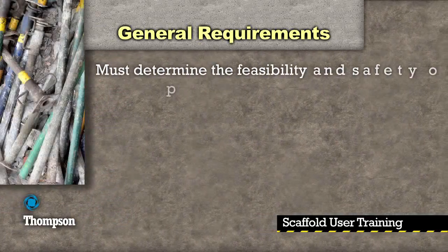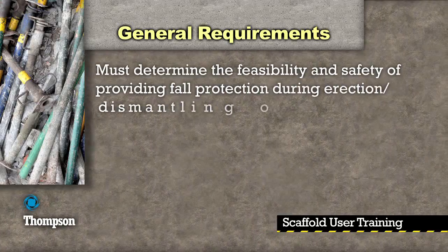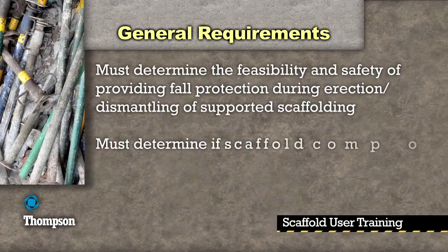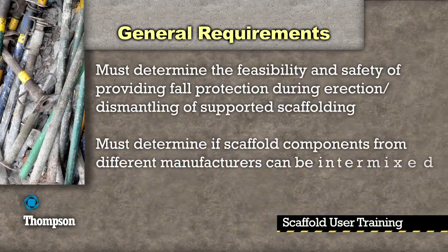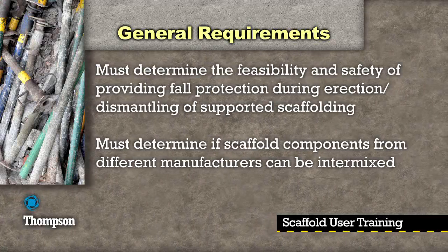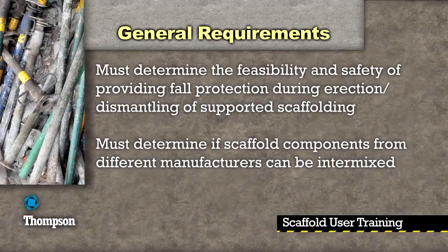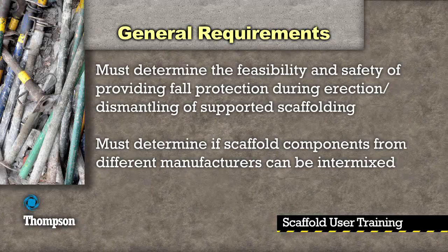Additionally, a scaffold competent person must determine the feasibility and safety of providing fall protection during erection and dismantling of supported scaffolding. He must also determine if scaffold components from different manufacturers can be intermixed.